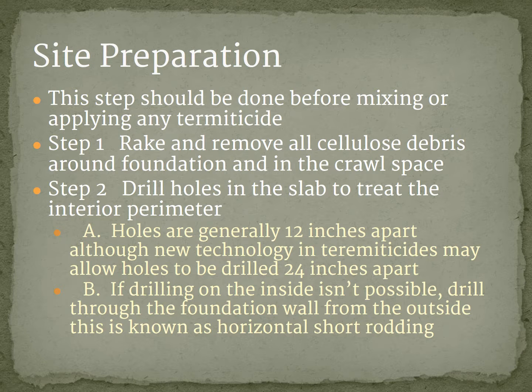If drilling on the inside isn't possible, you can drill through the foundation wall from the outside, and this is known as horizontal short rodding. Once again, that's what I would use doing a full termite treatment anyways, because I have no desire to go inside somebody's house and drill through their slab just to get termiticide under the slab. And most people have nice floors or tile or something that they don't want you to drill through anyways.